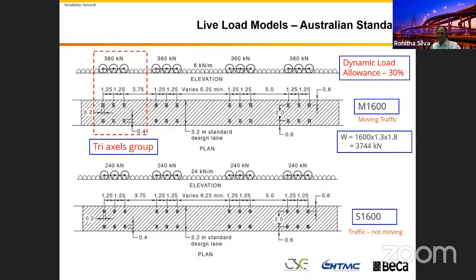I will share about with you. I wrote a paper in the sense group, and we designed those bridges using the AASHTO code. We use the lane load and a single small truck. But we tested those bridges for the truck train, like 10-wheeler trucks. We call it a truck train. They're placed next to each other, close to each other.